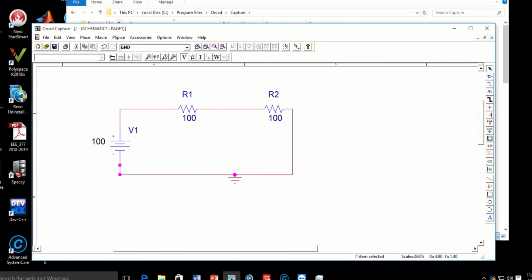One of the most important steps in the troubleshooting process during error and warning is assigning the net alias to the circuit branches. By default, Capture will assign random names for all connections in the PSpice circuit, which makes it harder to isolate the error connection if you have a large number of branches. Using net alias means you tag or label each branch with your own branch name. So in the example, I'm using plus VDC, net 1 and ground.